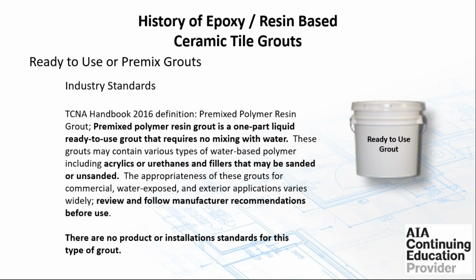There are no ANSI standards yet for this grout. This is being worked on, coming up with a standard of how the grout is being put together, whether it's an acrylic based or a urethane based, and how that's going to affect the ANSI standard on it. But if you're looking for an ANSI standard on this, there isn't one at this time. So it's best to check with the manufacturer to make sure where these grouts can be appropriately used without a problem. For the most part, we don't want to use these in a submerged application, or on an exterior application where it's going to be sitting in rain-soaked conditions or under ice and snow.